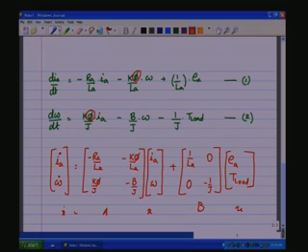Now, if phi is not a shunt, but let us say a series motor, in that case phi itself is a function of IA. So which means here phi becomes proportional to IA, which results in, let us say, this becomes now K1 IA.